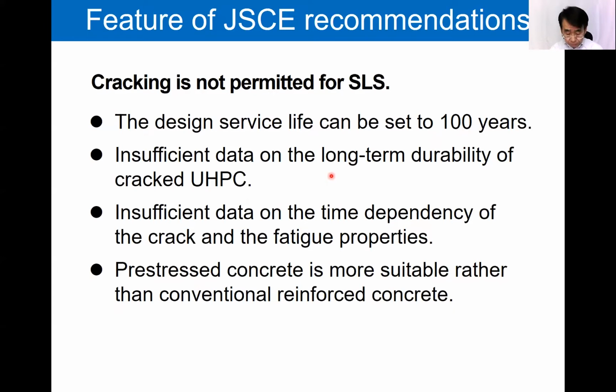However, there is not enough data on the long-term durability of cracked UHPC. In particular, corrosion of steel fibers at a crack may depend on the environment. There is also insufficient data on the time dependency of the crack and fatigue properties. Therefore, we had to be conservative to guarantee a 100 years design service life. Hopefully, in the future, more data will be available and cracks will be tolerated. When UHPC is applied to load-bearing members, this provision can be easily satisfied by introducing prestressing. Prestressed concrete is more suitable than conventional reinforced concrete to utilize the ultra-high strength of UHPC.